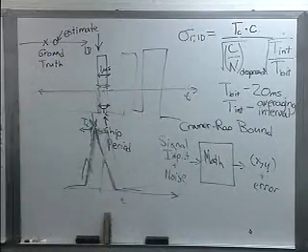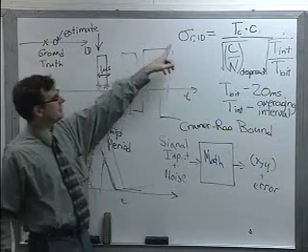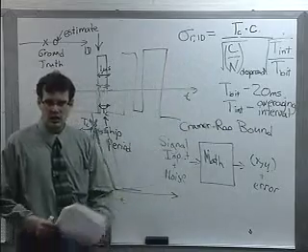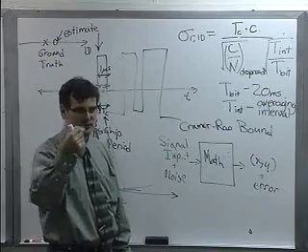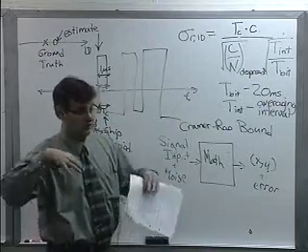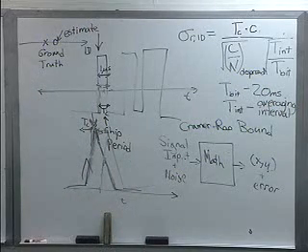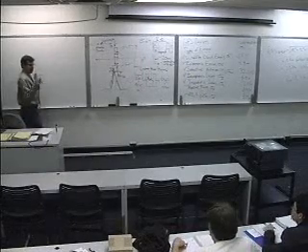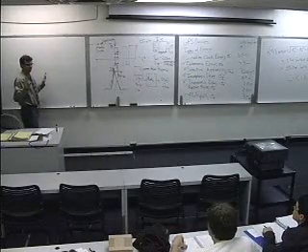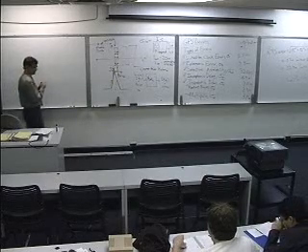But okay, one more thing before we continue on. This is not the actual formula. I put this as sigma sub r 1D. That is, if you're making a single measurement and trying to solve a one-dimensional position using this technique. We're using 4 dimensions: 3 dimensions for x, y, z, and then we need the 4th satellite to actually synchronize the system and get the offset like we talked about last time. So, okay, now pay attention. This is the part that confuses the heck out of students. So let me try to explain this as cleanly as possible.